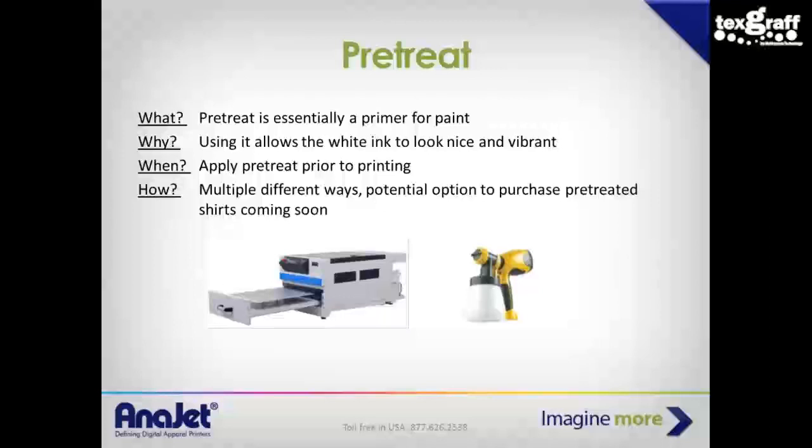Now, the key thing to recognize here is that once you've sprayed the shirt, it has to be dried, because you can't print right onto the wet pre-treat. So there's a few different ways to dry it. Everybody, like I said, I've been in this industry for 8 years, has their own way, whatever works for them. It seems to me that the most convenient way is to dry it under a heat press or a tunnel dryer if you have one. It's quick, takes no more than maybe 60 seconds to get it nice and dry, and you're good to go. People have hung them outside.